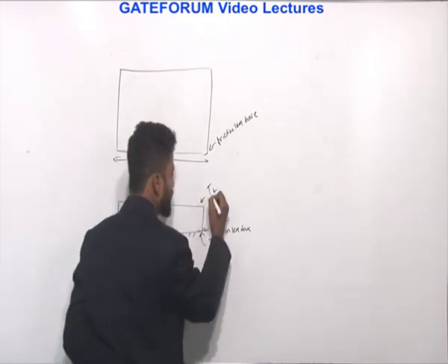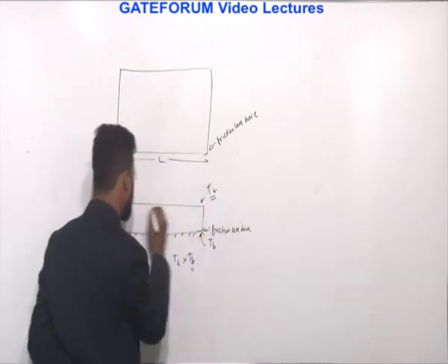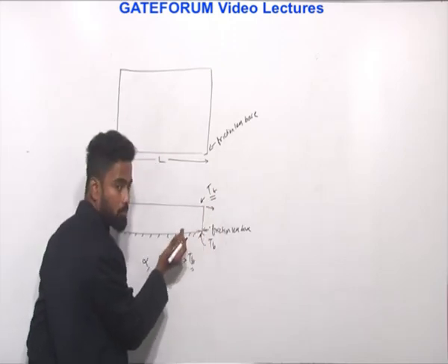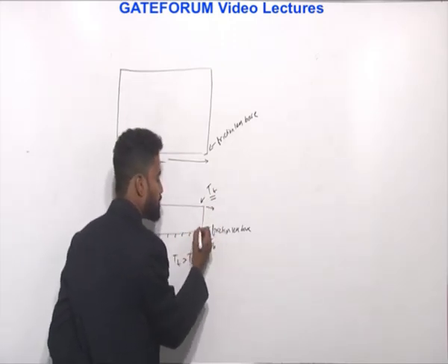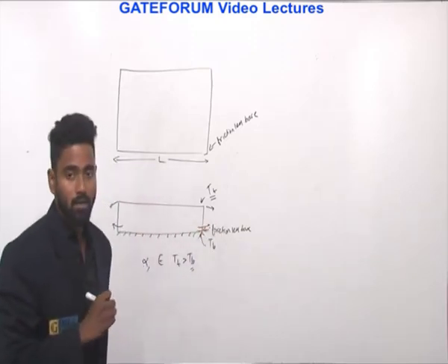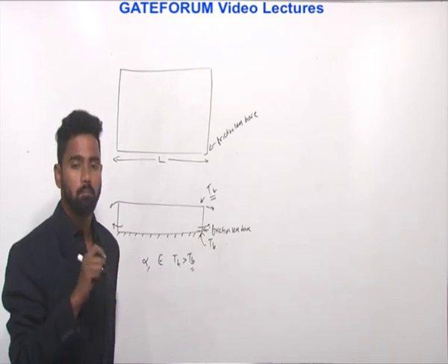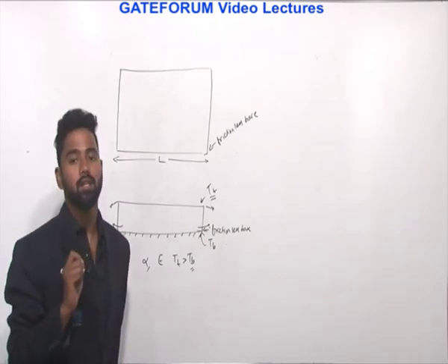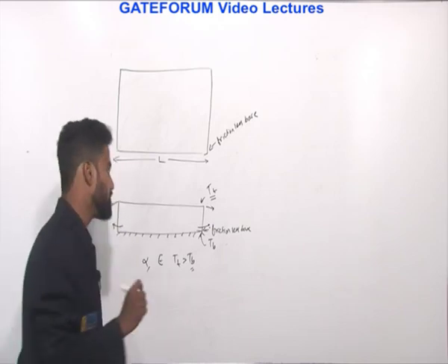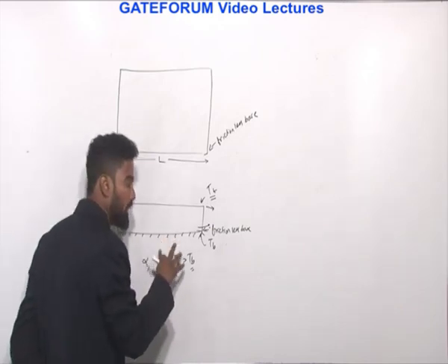What I am trying to say is, with increase in temperature, the top tries to expand and the bottom tries to compress, whereas the base provides stress in the opposite direction, right? That's how you calculate it. But read the question properly. He said frictionless base. The base is frictionless.